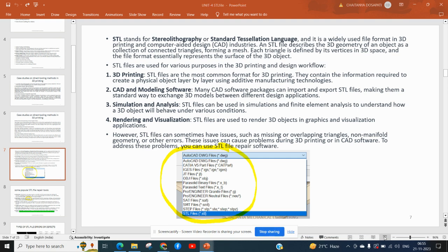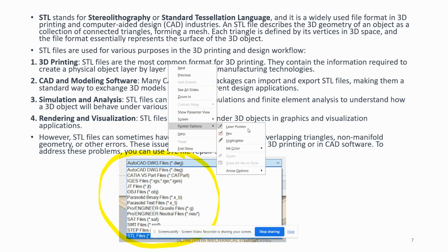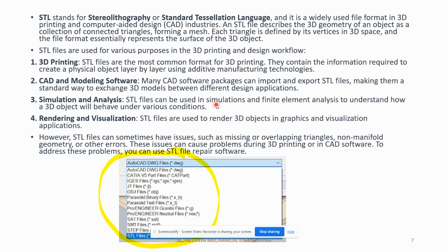process. Okay, so here you can see the three important designing steps. First, we need to create a 3D file by using any CAD software. Then we need to go for meshing. Meshing is an important process where we need to give the core structure a fine or medium mesh. Due to using this meshing technique, the 3D object can be converted into a number of facets.